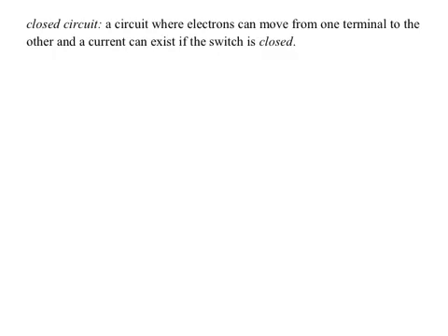But in the controller, are there 2 terminals in there? Or is it just one contact point? The two terminals are on the inside. So I'm sure you could have. Depends, though, and we'll talk about it in the next section, series versus parallel. If it was a series circuit or a parallel circuit, it would impact the way you have to orient your batteries and connect them.